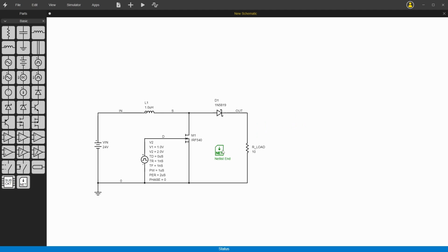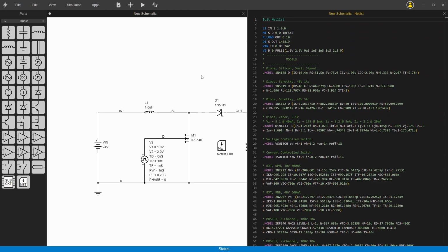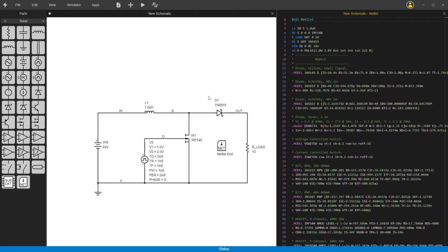If you remember from the overview first tutorial, the way that this builds the netlist, we can check out our netlist just by double clicking here. So this is the netlist so far. And if you remember the way that it builds the netlist, you can grab these and resize them, but it just loops through here and adds together all of the templates.